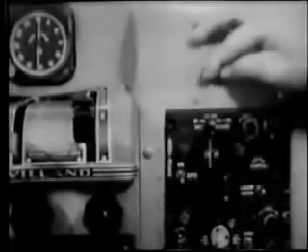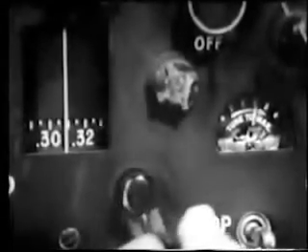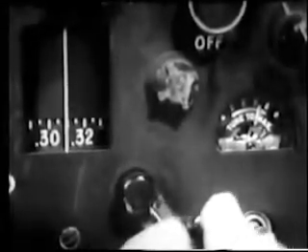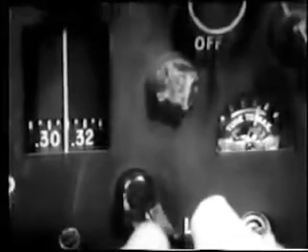The frequency span of this receiver is divided into 3 bands. Although calibrated in megacycles, notice it covers the desired range 190 to 1750 kilocycles. The tuning crank is used to select the desired frequency within the proper frequency band. Although the set can be tuned like your home radio, by listening to the signal, more accurate tuning is possible through the use of the tuning meter. Tune for maximum deflection.